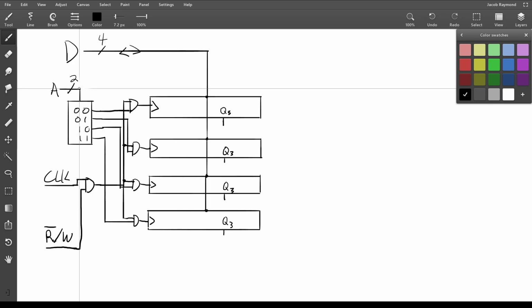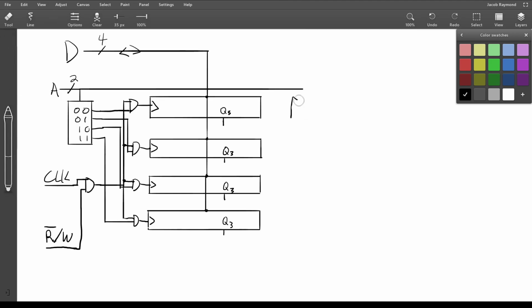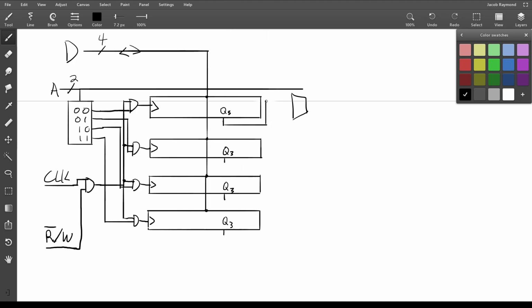So how can we properly choose which of these is correct? Well, with the multiplexer here, all we have to do is take this address and pass it in as the selector lines to just a small 2-variable multiplexer. Right? So we can take this input here and wire it up to the I0 input, and take this one here, wire it as the I1 input, take this one here as the I2 input.